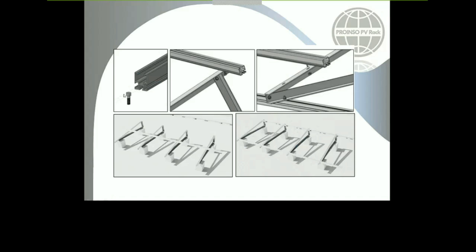For the rails as well, you slide the screw to the correct position. You already have some holes in the profile that have been designed just for the correct position, to avoid any distortions or misunderstandings in the position. As I previously said, just take the position of where the screw will be and put a little bit of washer, and when you ensure that the top rail and the bottom one are in the correct position and everything fits, tighten everything, screw everything.